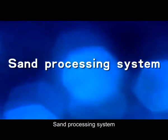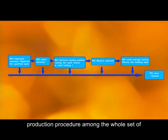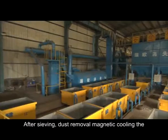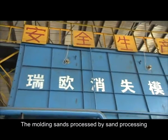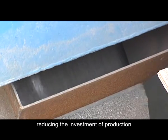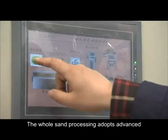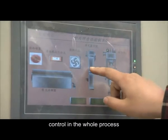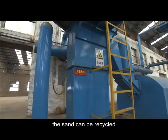Sand processing system. Sand processing system is a very important production procedure among the whole set of lost foam casting equipment. After sieving, dust removal, magnetic separation and cooling, the sands are stored for the production of casting. The molding sands processed by the sand processing system can be recycled completely, reducing the investment of production. The whole sand processing adopts advanced PLC control and is equipped with sand temperature control in the whole process. After sieving, dust removal and cooling, the sand can be recycled.